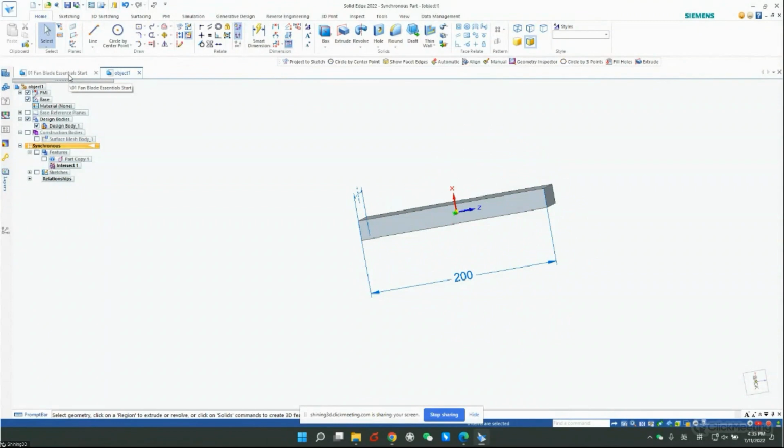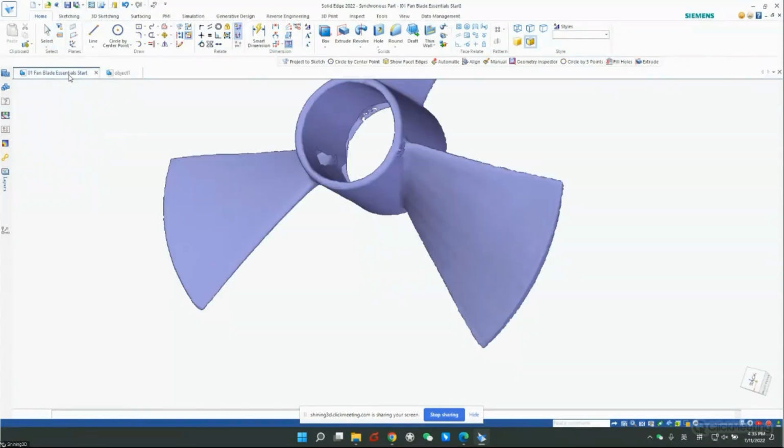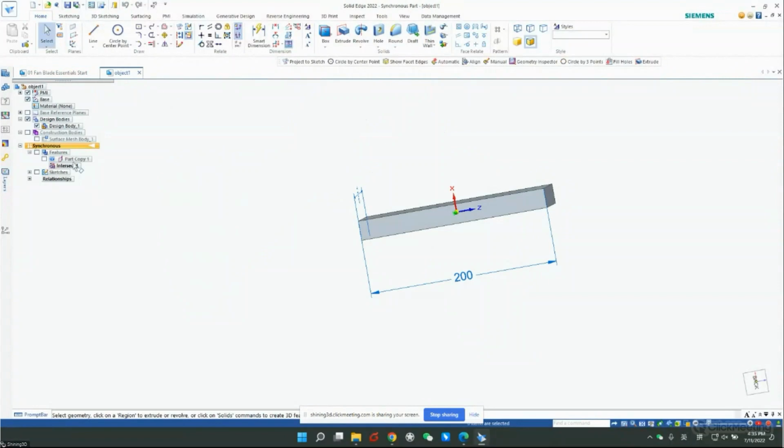So this is one way to do your design: for some of the simple features, you can just fit features and combine all the surfaces. You fit it to a solid body, then just create the model you want. And there's another way to do so, which is using the sketch that we constructed before.